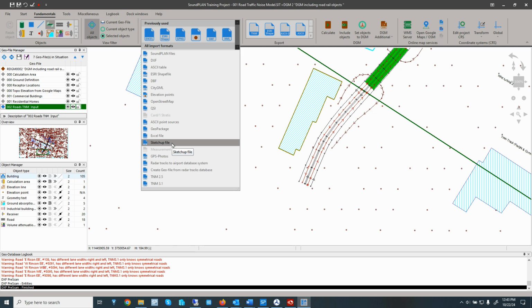I can only recommend not to go overboard. For interior modeling, try to simplify the interior room geometry. Overloading the indoor model with an extremely detailed SketchUp model will result in extremely long calculation times.